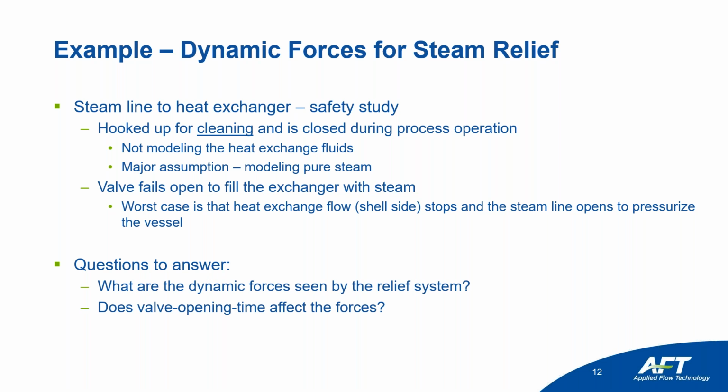So the questions to answer are, what are the dynamic forces seen by the relief system? And then, are those affected by valve opening time? Because in our last example, valve closing time didn't really affect things. But in this case, how does valve opening time affect forces?